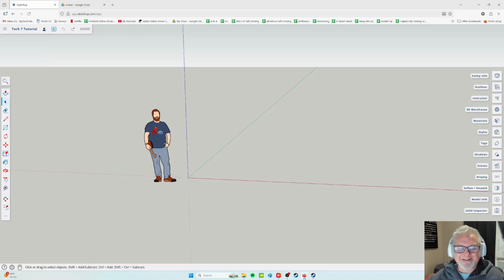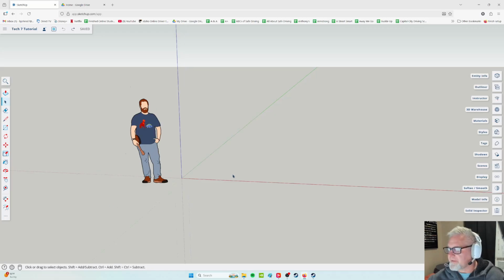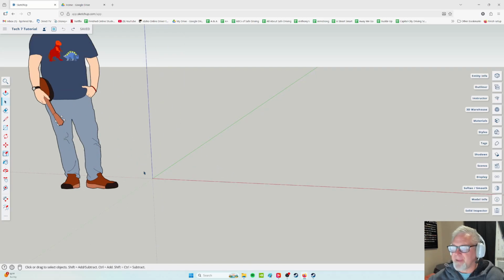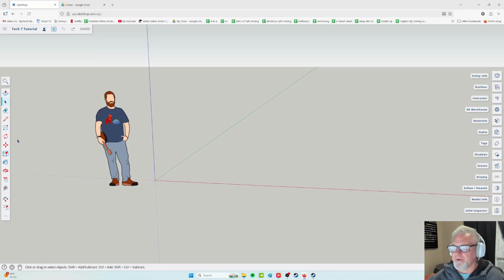All right, so where all these lines come together, this is called the origin. So if I'm making something, one thing especially, or the first thing, I like to start at the origin. So if I'm making a rectangle or a square, I click on the rectangle tool and I just roll my mouse. I don't click yet. Roll my mouse, see how it turns into a dot? And it even says, hey, you're on the origin. Super useful. And SketchUp does a great job of helping us know where we are sometimes. Tells us when we're lined up, when we're even, parallel, etc.